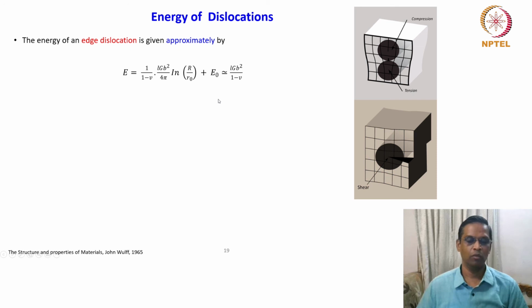You look at what is the modulus given for a plane stress problem and a plane strain problem. Okay, very important. So the moment you go to the plane strain problem, this kind of 1 minus mu term comes into elasticity theory. We are not getting into the details, but I'm just giving you a clue.